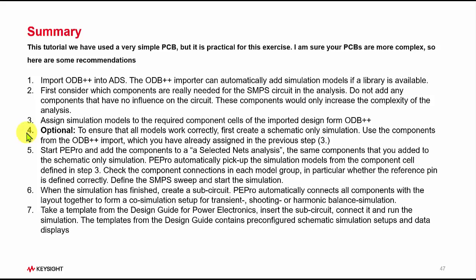To ensure that all models work correctly, first create a schematic-only simulation. Use the components from the ODB++ import, which you have already assigned in the previous step. This is the optional topic in this tutorial, but I will show it in more detail after this slide.